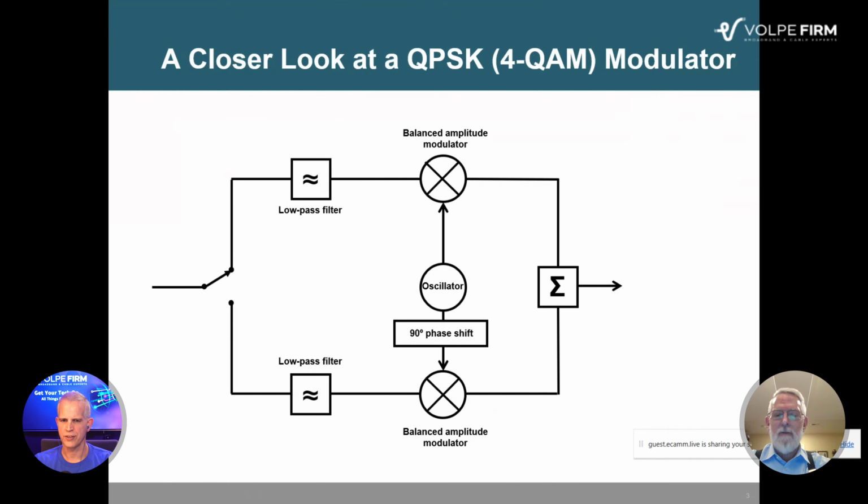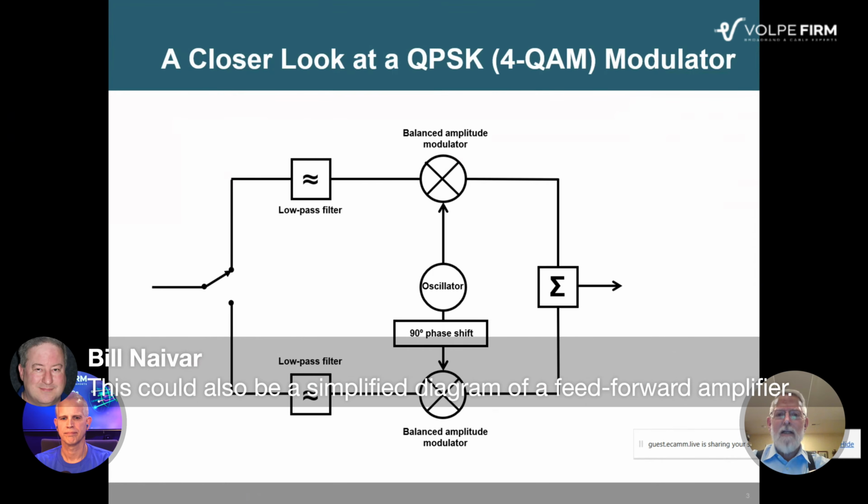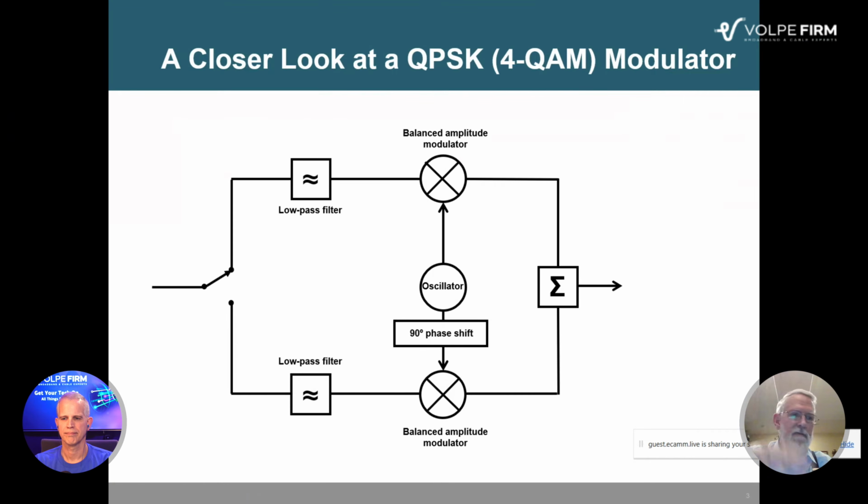So that carrier that you're referring to, is that part of the underpinnings of what we call single carrier QAM, or is that carrier not part of what we're calling single carrier QAM? What it is, you start out, if you turn off the modulation and just have the output present, you'll have a CW carrier at the center of the channel. As soon as you apply modulation, the carrier is suppressed in the center of the channel. It's still there, but it's way, way, way down, several tens of dB below the amplitude of the digital channel power.